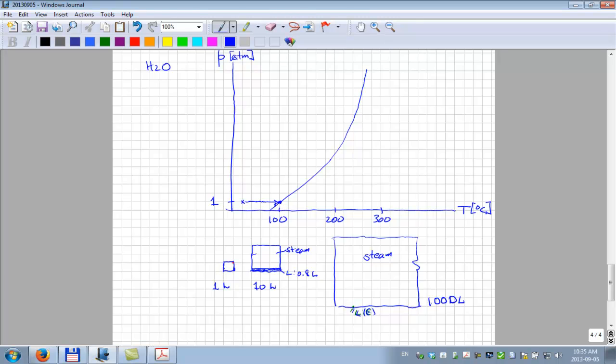And this line passes, for the different temperatures, through the pressure where you get the same phenomena going on, that the water can split into a vapor or liquid or some mixture, it doesn't care. This is called the vapor pressure curve. Okay. It's where a liquid will form its first bubble, or a gas will form its first drop. Okay? The vapor pressure curve.